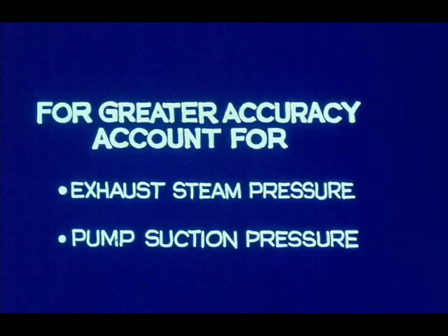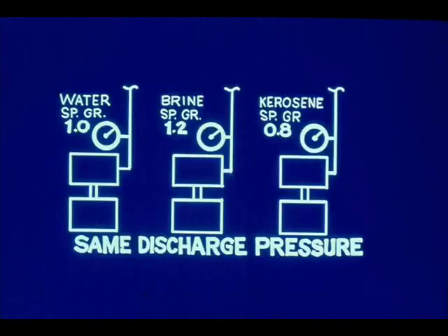Where great accuracy is required, such factors as exhaust steam pressure and pump suction pressure must be taken into account. But the formula is accurate enough for most purposes. Note that it was not necessary to know the specific gravity of the liquid being pumped. The discharge pressure of a steam-driven reciprocating pump is the same for any liquid.